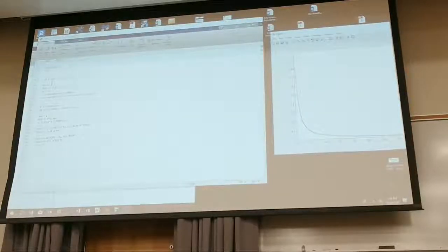Let's go 2 to the 12th, or I mean make 2 to the 12th. By this time I think it's going to be indistinguishable. See what's going on here, guys? This is real important. Now we can actually get sample data, finite interval time sampling, and if we adjust it by that factor, 1 minus e to the minus j omega, adjusted omega times Ts, divided by j omega, where omega is adjusted, now we literally have the Fourier transform of that signal that we can look at.